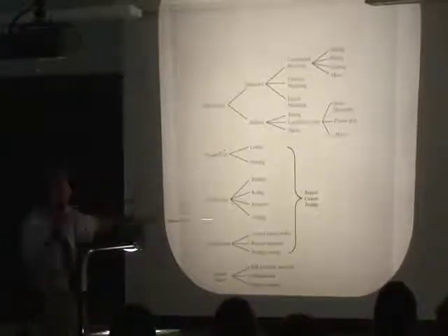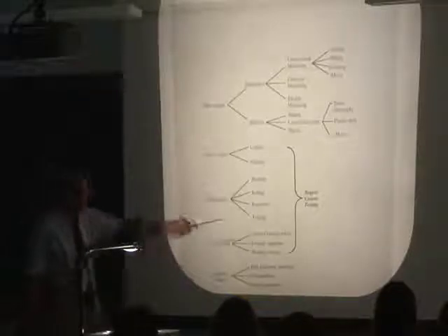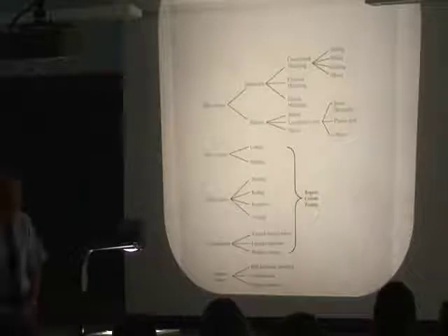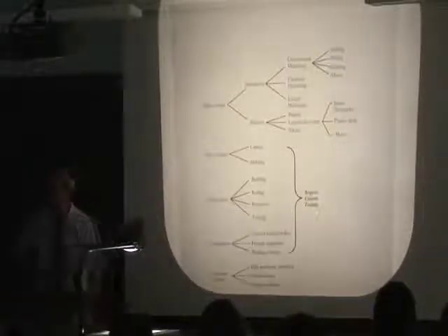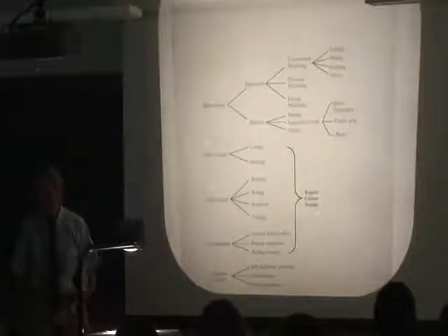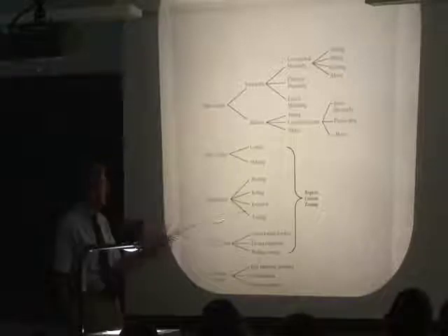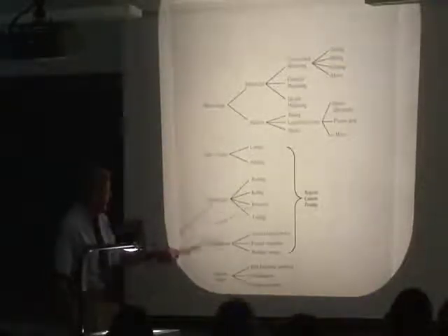Now, all of these down here have the requirement that they require custom tooling. And so it's unusual to use these if you're only going to make one of a kind or maybe two of a kind. Not always true. There are some products of which you make only one, for which you really must cast it. And that's true for some others.